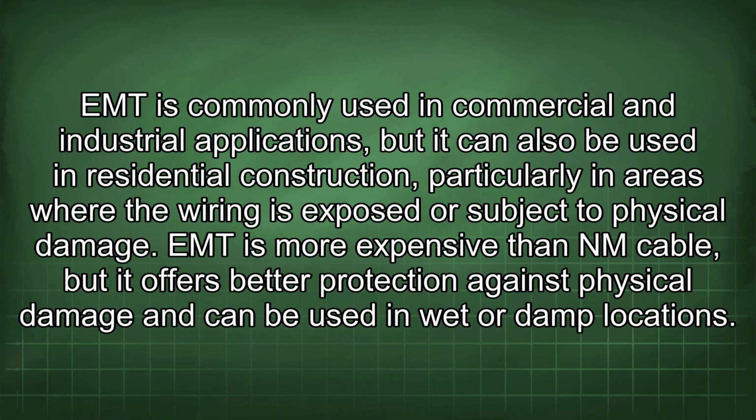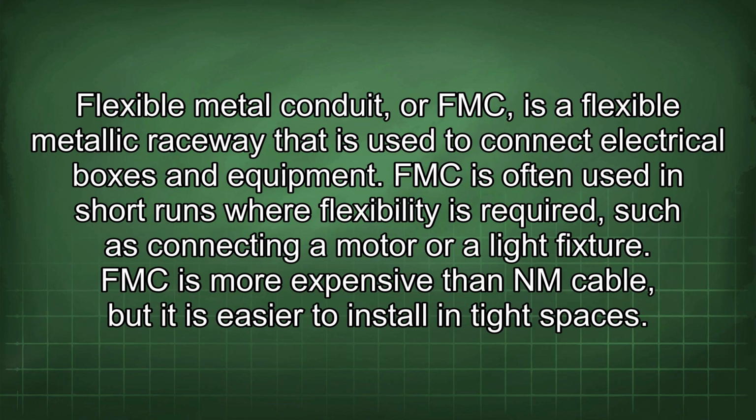wet or damp locations. Flexible metal conduit, or FMC, is a flexible metallic raceway that is used to connect electrical boxes and equipment. FMC is often used in short runs where flexibility is required, such as connecting a motor or a light fixture. FMC is more expensive than NM cable, but it is easier to install in tight spaces.